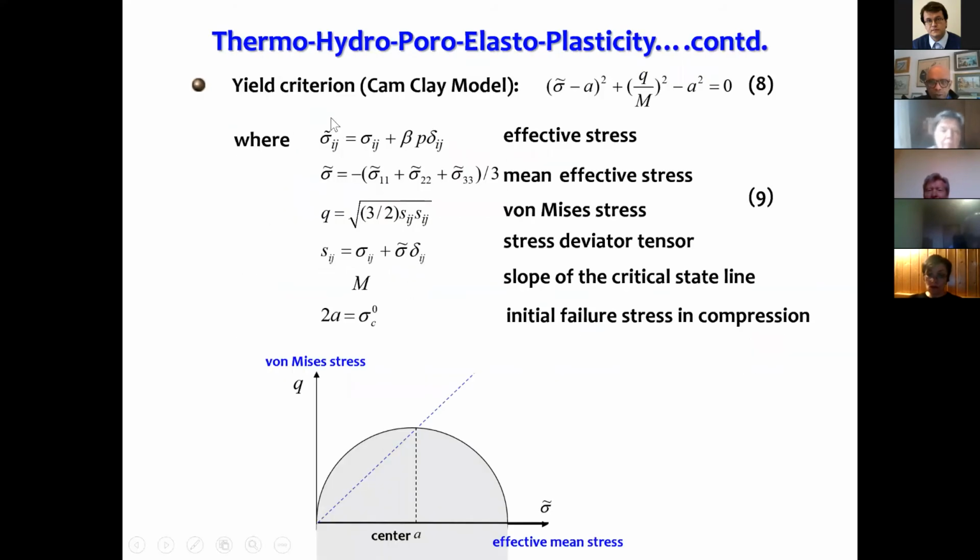So your yield criterion is something like this. These are basically the isotropic stress and the von Mises stress is there as well. The yield surface is basically governed by this dotted line and this surface. So it can keep moving. The isotropic hardening can make the surface move, and that's also taken into consideration.